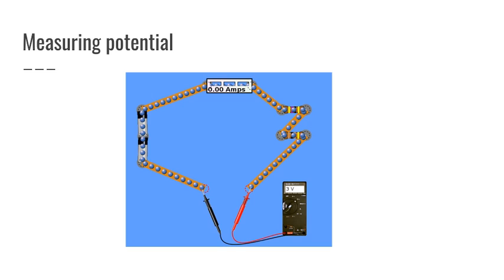The next change to the circuit we made was to replace one of the ammeters with a voltmeter. A voltmeter records the potential difference across its probes. Due to the combined voltage in the batteries, the potential difference at this point in the circuit is 3 volts. The ammeter's reading has dropped to 0, however. This is because the internal resistance of the voltmeter is incredibly high, and as the current is being forced through what is effectively a very high resistance resistor, the value of the current becomes very close to 0.